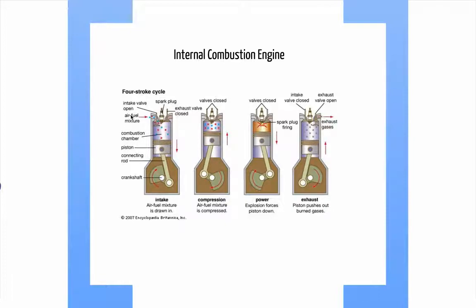First, there is an input valve through which the air-fuel mixture comes in. There's a spark plug which initiates an explosion, as we'll see soon. And there's an exhaust valve, which is closed at the very beginning during intake. So the air-fuel mixture comes in, which pushes the piston down. This piston is connected to a crankshaft, which turns the wheel, the axle.